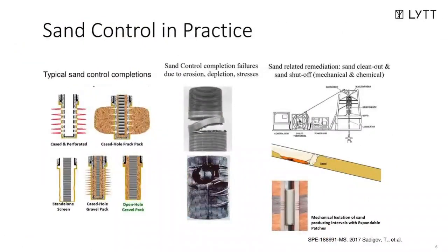Let's talk about today's approach. The typical approach in the industry to circumvent the challenge is to first install sand control completions like gravel packs that act as filters to prevent sand from being produced. These are, however, quite hard to install several kilometers underground, and changes through the life of the well also lead to challenges in maintaining its integrity, eventually leading to sand production.